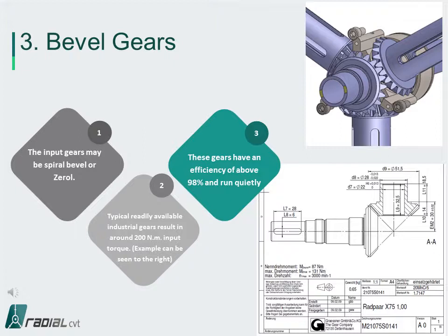An additional benefit of the Gen 2 radial CVT is that the central bevel gears drive 3 radial bevel gears and therefore handle 3 times their rated torque, while it is only necessary to design the central bevel gear for 3 times the normal revolutions of that experienced by the radial bevel gears, assuming a 1-to-1 ratio.